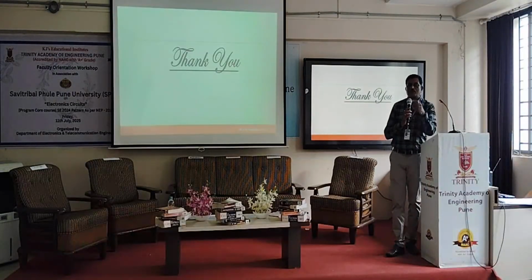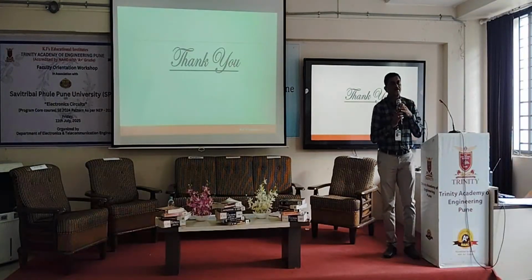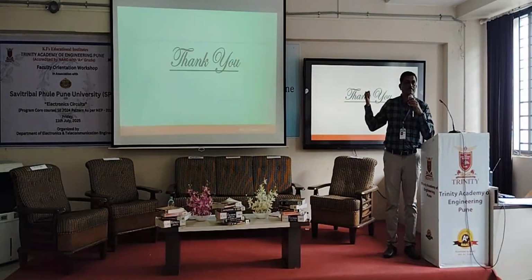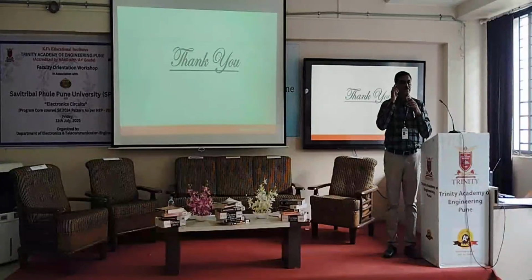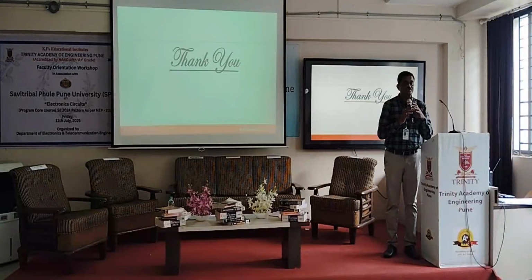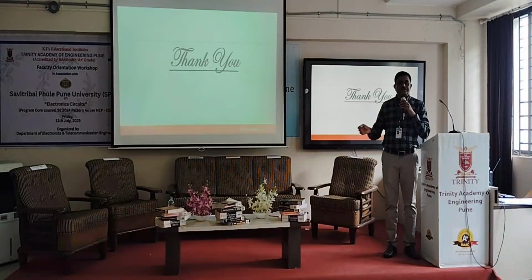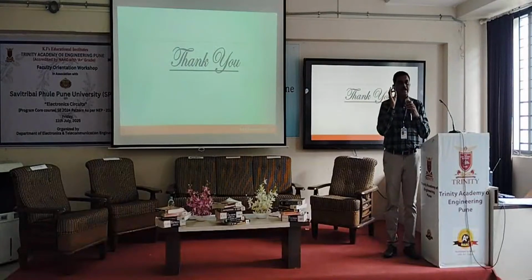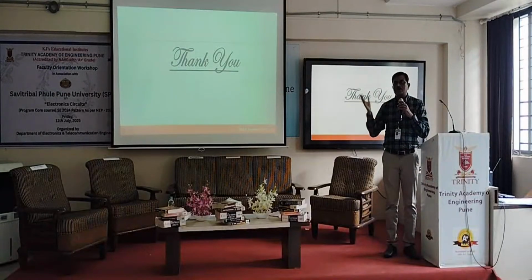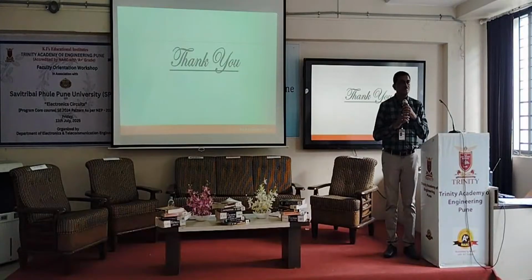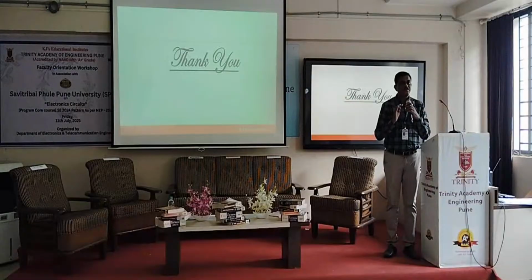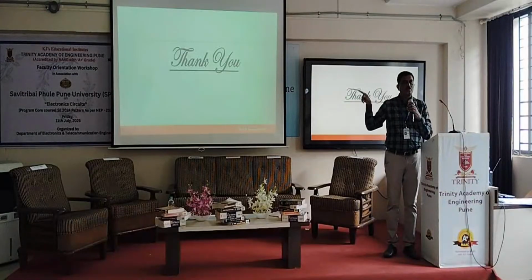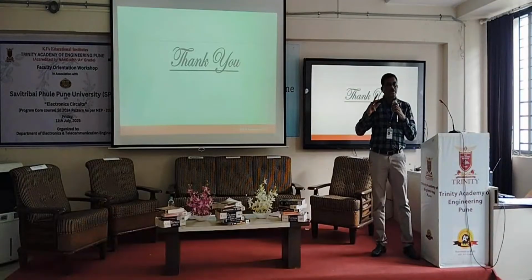The second practical is related to this unit number 4, which is the square wave generator. For the square wave generator, frequency should be given from the design point of view. Assume the value of C, calculate the value of R, and observe the output waveform. Assume the value of C, calculate the value of the feedback resistor, and there are again two resistors, R1 and R2.